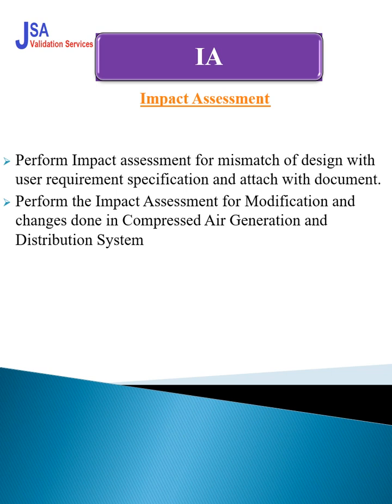So for that you have to do the enhanced design review, prepare the new user requirement specification, and enhance the design qualification also. Then perform the impact assessment on the modification changes done in the compressed air distribution system. What is the impact on SOPs? What is the impact on qualification protocols? What is the impact on other areas? What is the impact on the process? So all impact you have to assess. That is called the impact assessment.